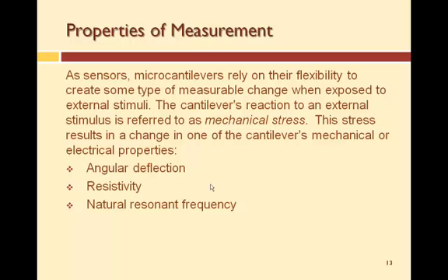It's going to change, right? So all I need is a position-sensitive detector that detects the change in the reflected light, and we can understand how much that cantilever deflected. So in the case of a coating, if you have more stuff absorbing into it or less stuff absorbing into it, it'll deflect at different angles, and you can measure that.